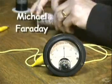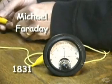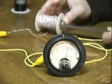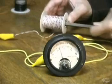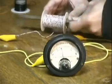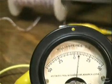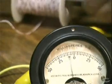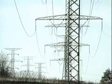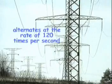Michael Faraday found out in 1831 that when a magnet moves in a coil of wire, an electric current is produced. If we look closely at the movement of the magnet and compare that with what is happening with the voltmeter needle, we see that when the magnet goes into the coil, the needle moves one way, and when the magnet is pulled out, the needle moves the other way. So as the magnet moves in the coil, the current alternates between two different directions. In the United States, the current alternates at the rate of 120 times per second for 60 complete cycles per second.